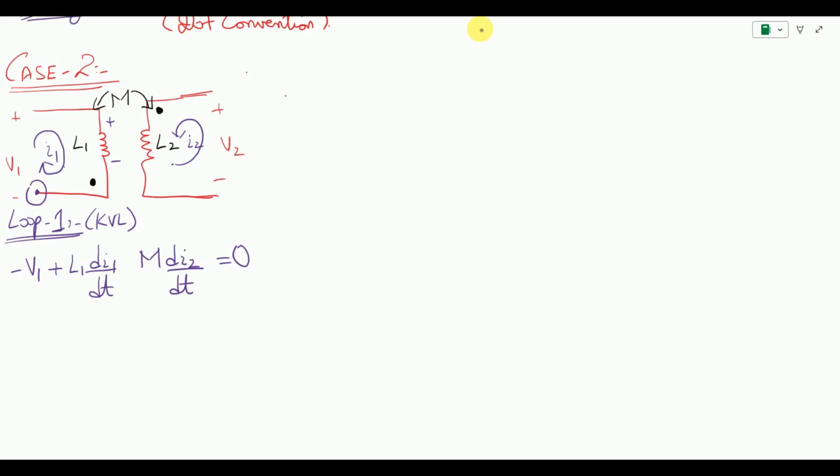In order to find the sign, I'm going to look into the current in the second circuit. So this is my circuit number 2, again for reference. This is my circuit number 1. So in circuit number 2, I see that current is entering into this position. So I can say if the current is entering, my polarity here will be plus, and here it is going to be negative. So my equation will come out to be negative M di2 by dt, and this is my equation over here. Again, to highlight, these are my terminals. So these are my dot conventions over here.